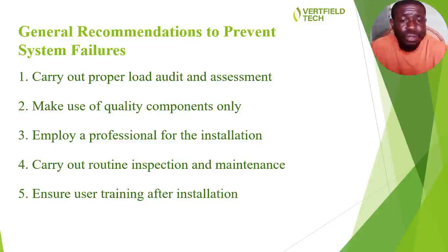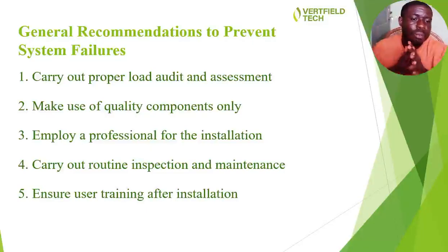Now, let's look at general recommendations to prevent system failures. Carry out proper load audit and assessment. Make use of quality components only. Employ a professional. Do not just get anybody, not any technician, not any electrician can handle a solar system. Okay, carry out routine inspection. Your solar system should be inspected and maintained every three months.